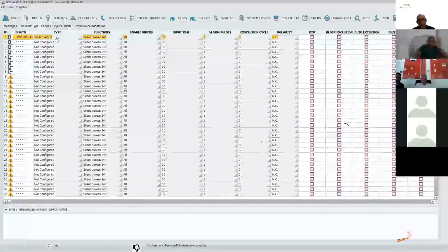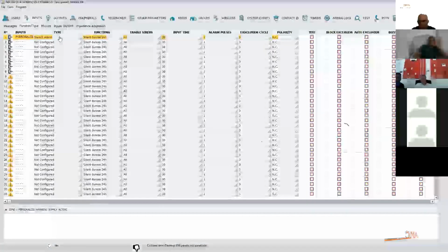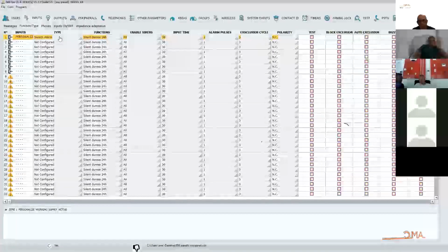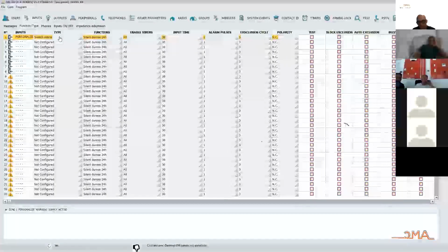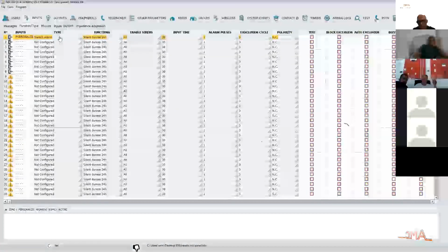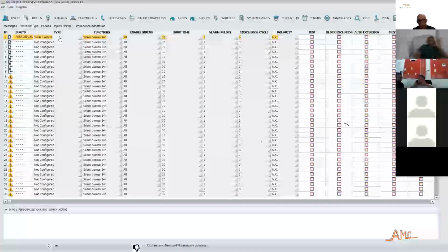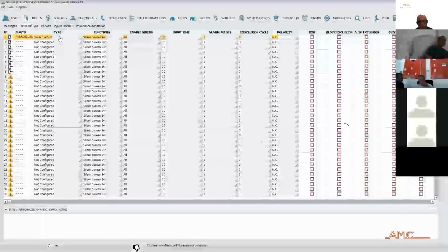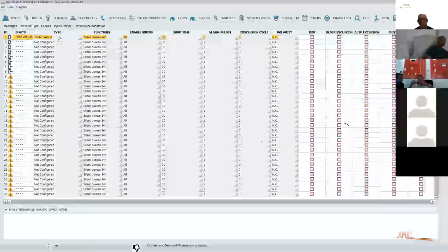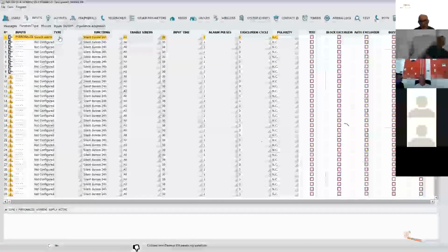Switch alarm, I want to explain switch alarm. Switch alarm is a fast counter. Normally, this option is used for vibration sensors, shock sensors, for all types of sensor where there is a fast pulse counter. Normally, this system works with a special capture that captures the timing of the pulses.